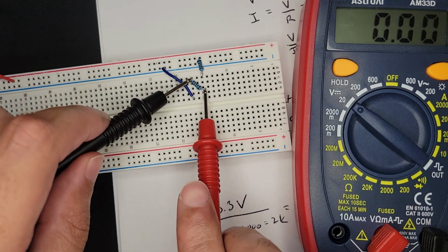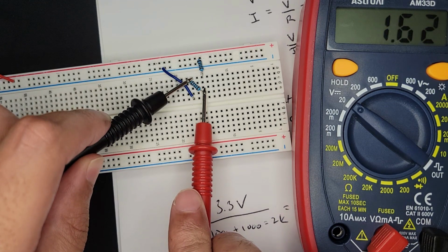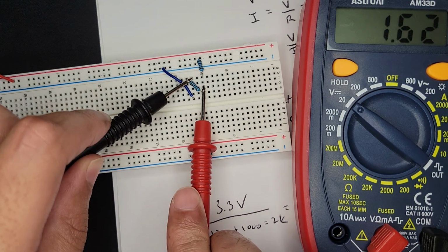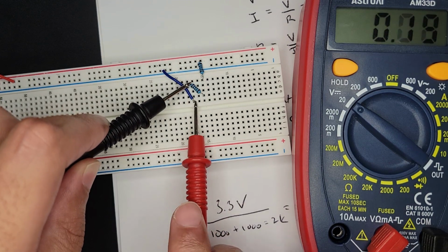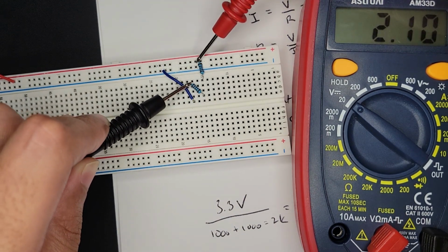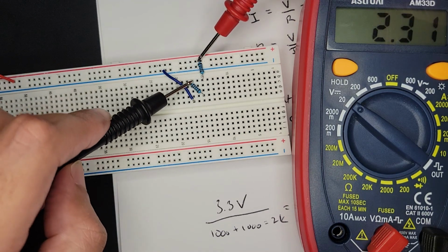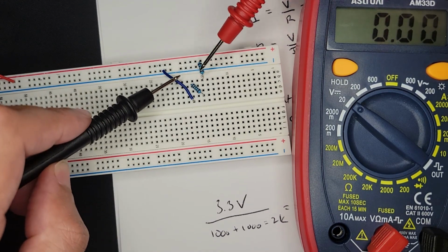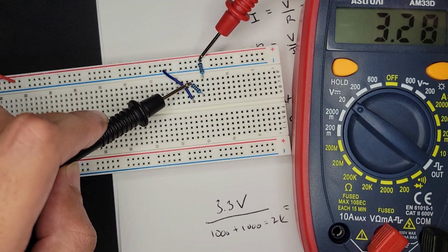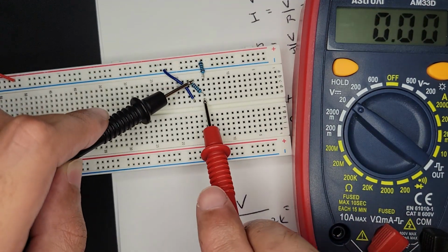Or we could take this resistor by itself, which we know is a 1000 ohm resistor, and divide our 1.65, and we get the same result, right? 1.65 divided by 1000 is 0.00165 amps, which becomes 1.65 milliamps. So we can kind of see the math in live action here, working the way that it should. By taking the voltage across two of these resistors, it's basically getting the voltage difference. And we can see that both of them are consuming the same amount, which makes sense because they're both the same resistance values.